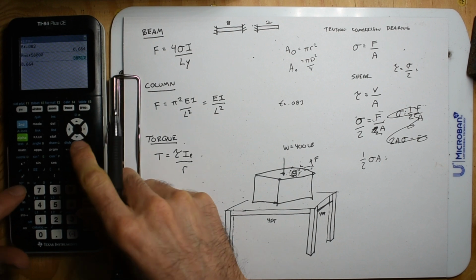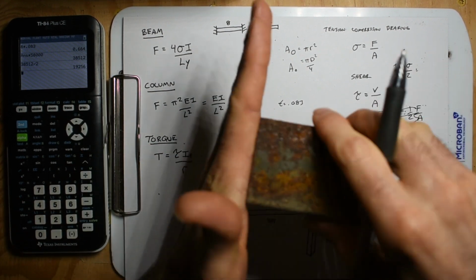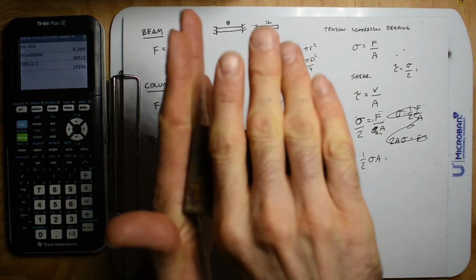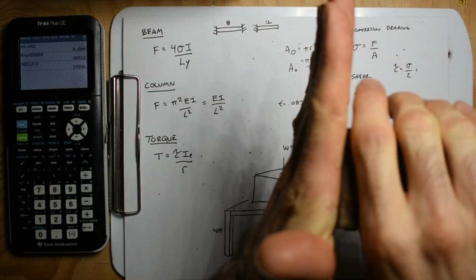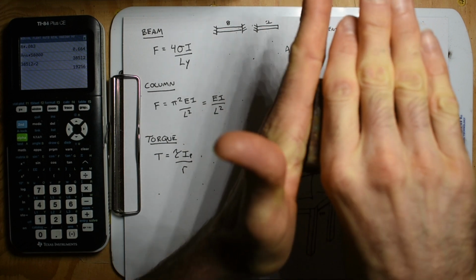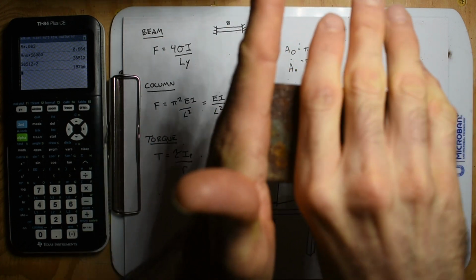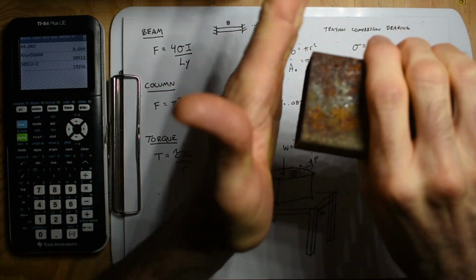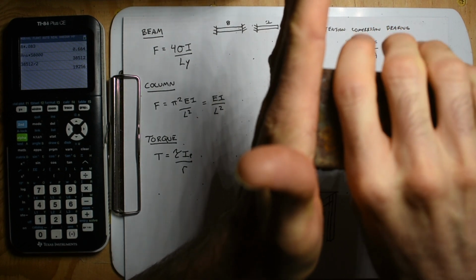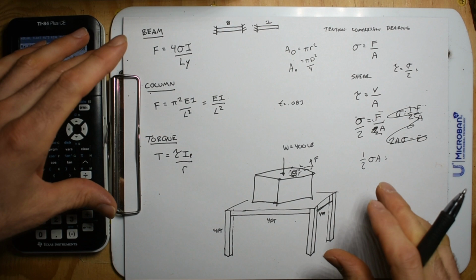So that 38,000, easy peasy, we just divide by 2. And so if you drove a car on a cantilever, a single cantilevered bridge, you could put 19,000 on it, so you'd weld this. That's amazing. And if you welded this to a wall and then started hanging something, you can't hang that cab of that semi, but you can hang 20,000 pounds. That's amazing. All right, so that's 2 equations down, and we got kind of 3 more to go, and that's it. That's material mechanics wrapped up in a nutshell.